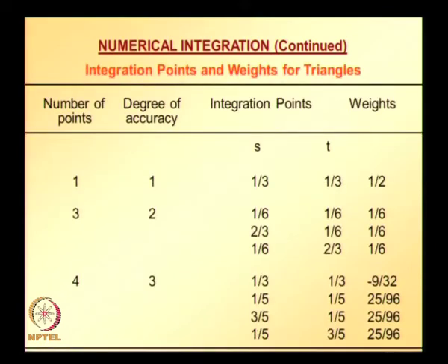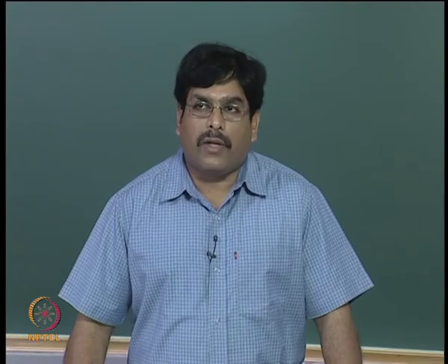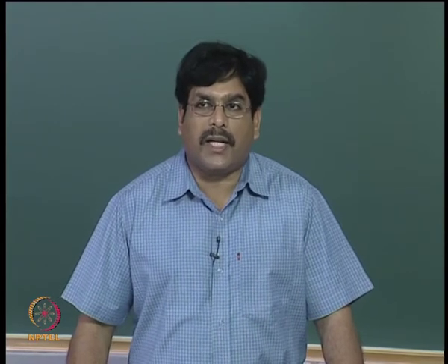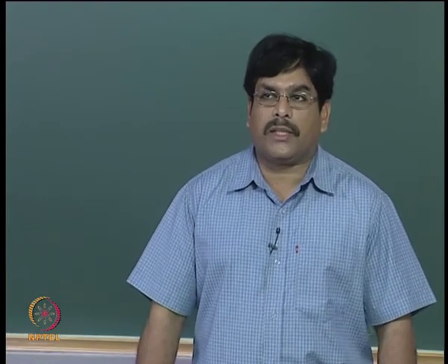So, integration points and weights for triangles. If we decide to use one point integration, then we need to evaluate the integrand at s equal to 1/3, t equal to 1/3, and multiply with weight half. If the number of integration points is selected as 3, then we need to evaluate the integrand at 1/6, 1/6 and multiply with weight 1/6,